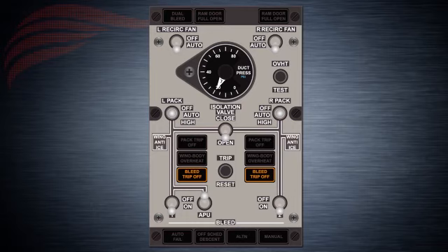Similarly, if bleed air pressure increases beyond 220 psi and an overpressure condition is sensed, the same light illuminates. When a trip-off condition occurs, the bleed air shutoff valve is closed irrespective of engine bleed air switch position. The bleed trip off light may only be extinguished by pushing a trip reset button, located in the middle of the air conditioning panel.